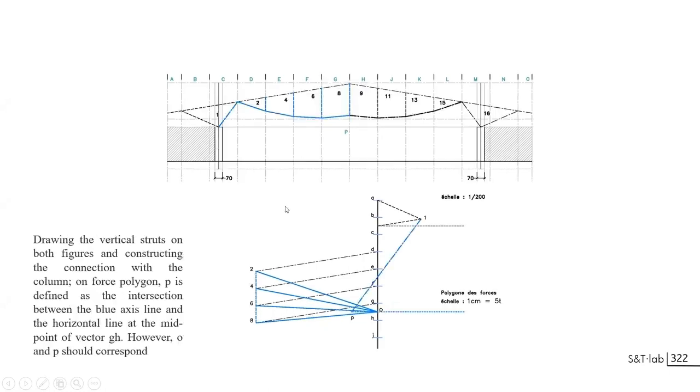If you are trying to connect this structure with the column here, you have to build another force polygon here. I will just define it as being vertical. I know this direction here, and here. So parallel here giving that line, a parallel here giving that line. So I know the intersection point here, and I know this direction here giving the third line.